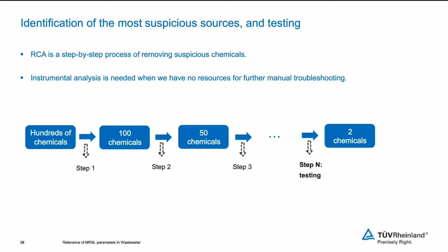The next one is specific, I guess, to India. Shivendra, the question is, what do you observe in terms of wastewater analysis or sludge analysis for facilities in India where ZLD is required? Shivendra, do you want to share some feedback on that? When we are talking about ZLD, the Zero Liquid Discharge unit, in the last year, after June, this additional information has been added. Basically for ZLD, the only sampling points are raw wastewater and sludge to be tested.